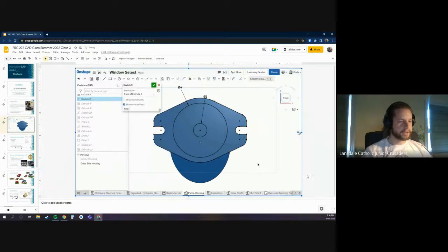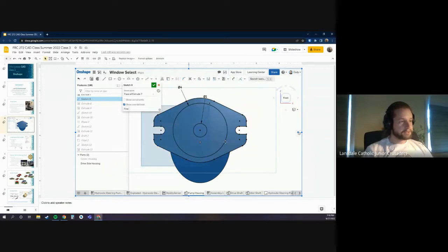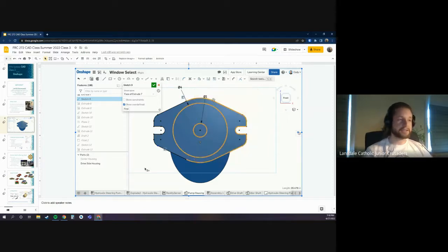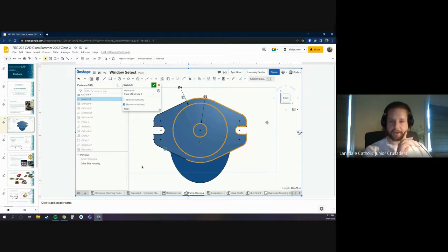So this is just a little animation that somebody from the Onshape team recorded. If you look, when this person, their name's Cody, clicks and selects to the right, they only are selecting the things that are fully within the box, completely within the box. Now, when they click and select to the left, they select all the things that are even touching the box. And it's an important distinction. It'll allow you to more correctly and easily select the geometry in your sketches that you want to select.